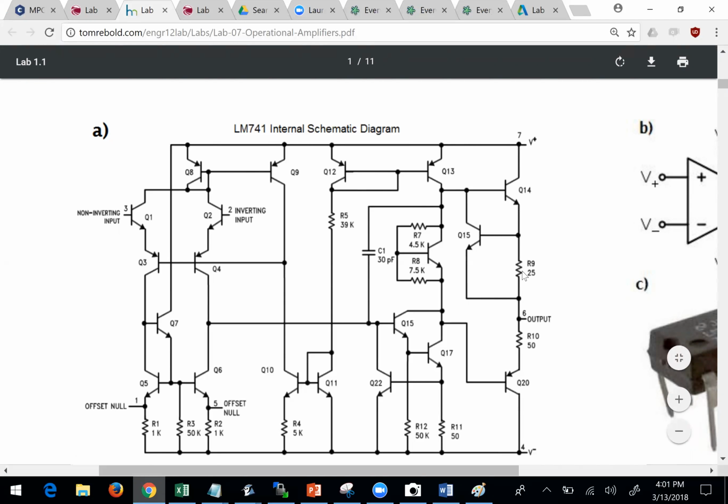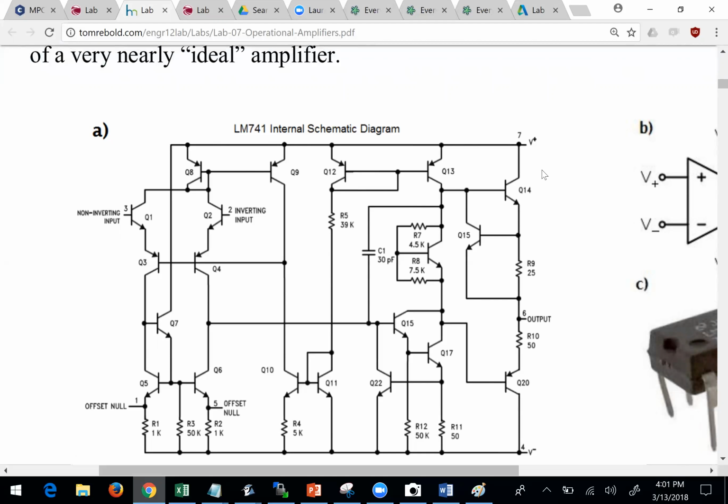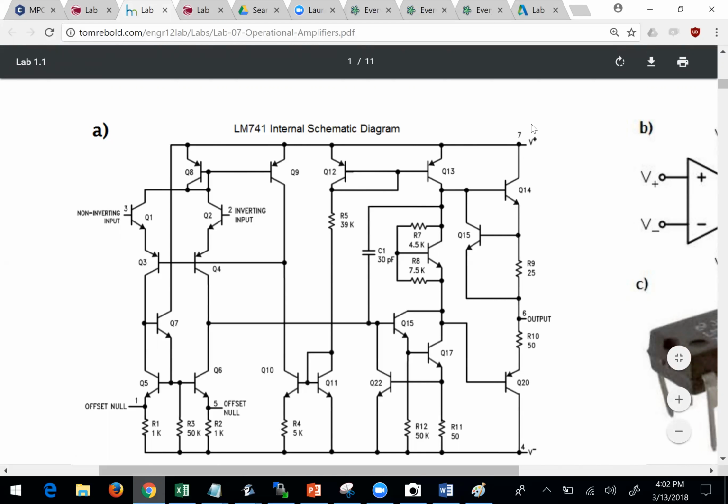That's going to keep you at least a 0.7 volt drop from that PN junction inside the transistor, which I call a diode drop, but it's actually part of the transistor, because the transistor is an NPN sandwich. And so the highest you can get at this point is going to be 0.7 volts below your voltage of V plus.